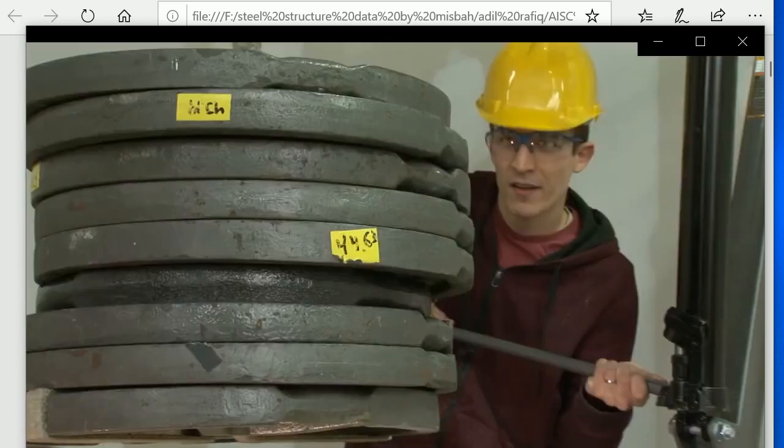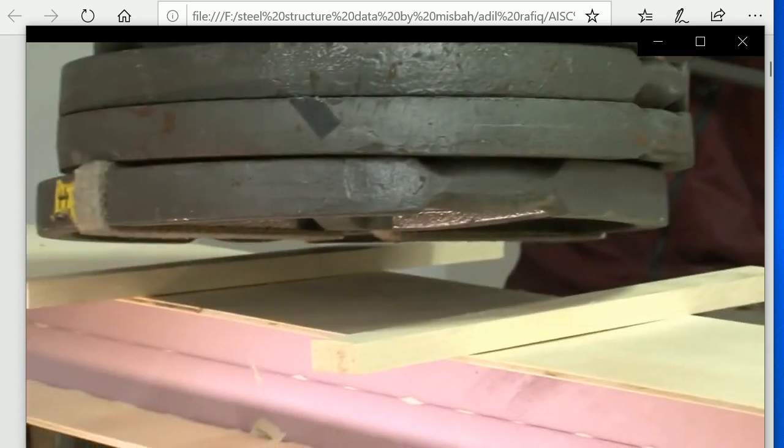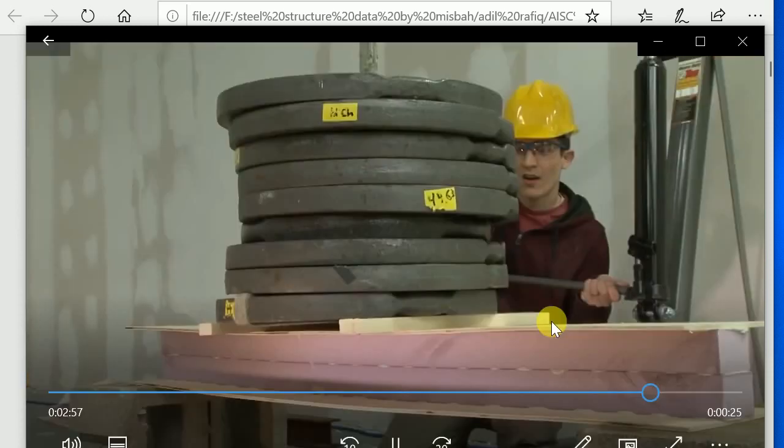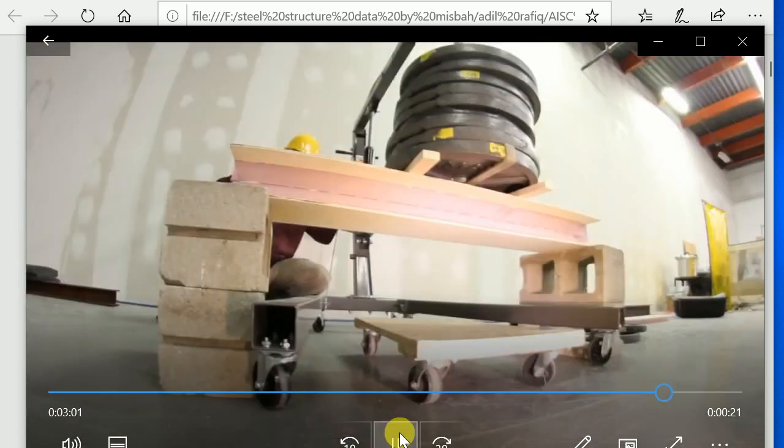Nice and slow. Oh yeah, that's holding. So for only a double increase in the height, going from 1 to 2, we got more than double the strength increase. Like an I-beam. This is the principle of how things work.